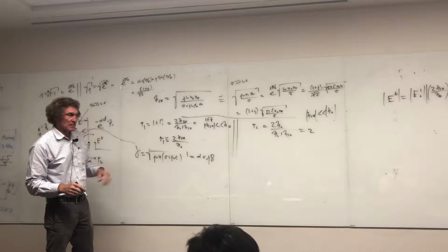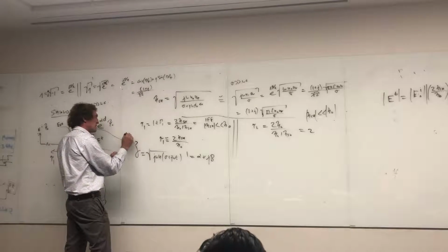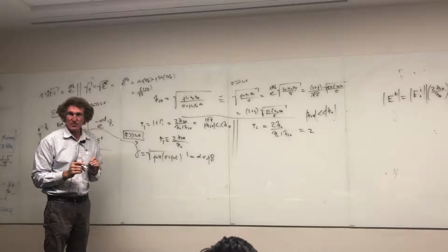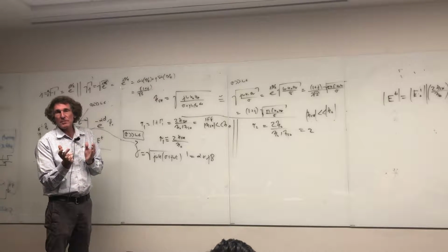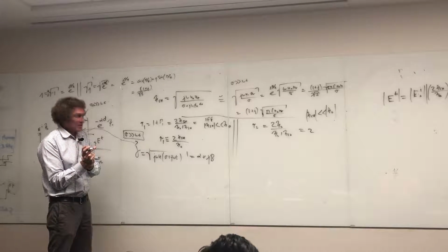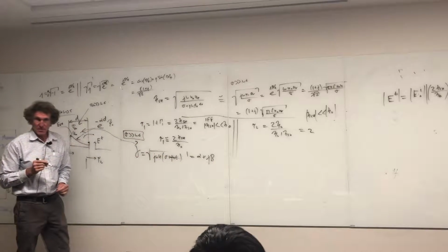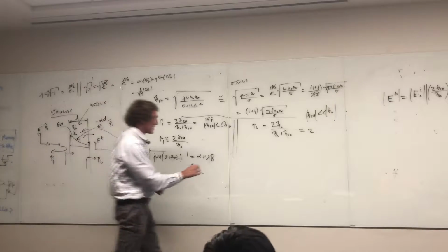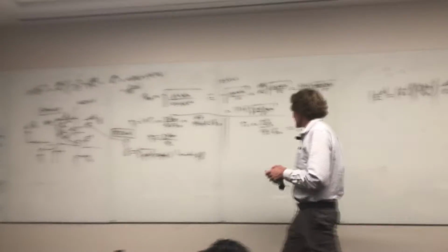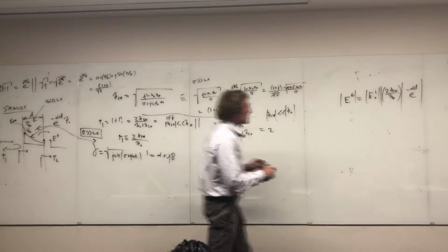All right, now we make the assumption. If I assume that sigma is much greater than omega epsilon, that's almost always the case for any decent shield, or else you wouldn't be making it. You wouldn't use a material where this wasn't the case. It would be foolish if you're making a shield. Now, follow me on this. Do you all see how this cancels right here? If that's the case, what happens? I want to make sure you all see this. If that is the case, then this becomes equal to, matter of fact, let me write it up here.